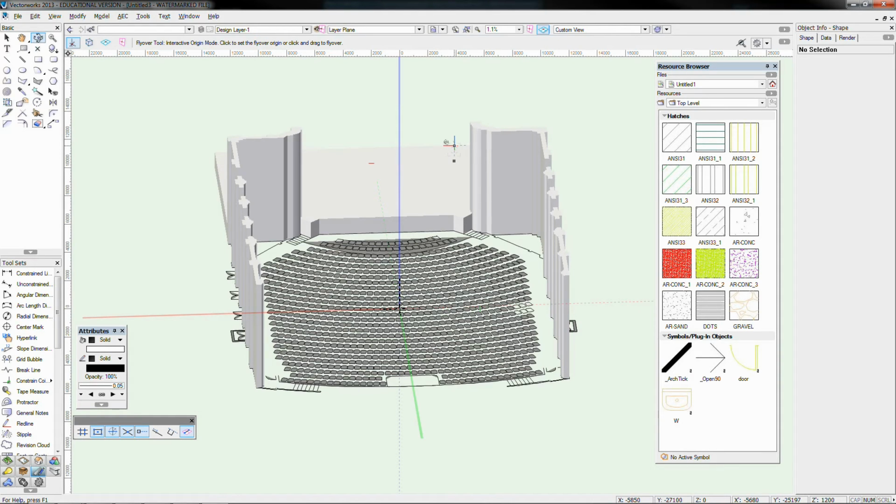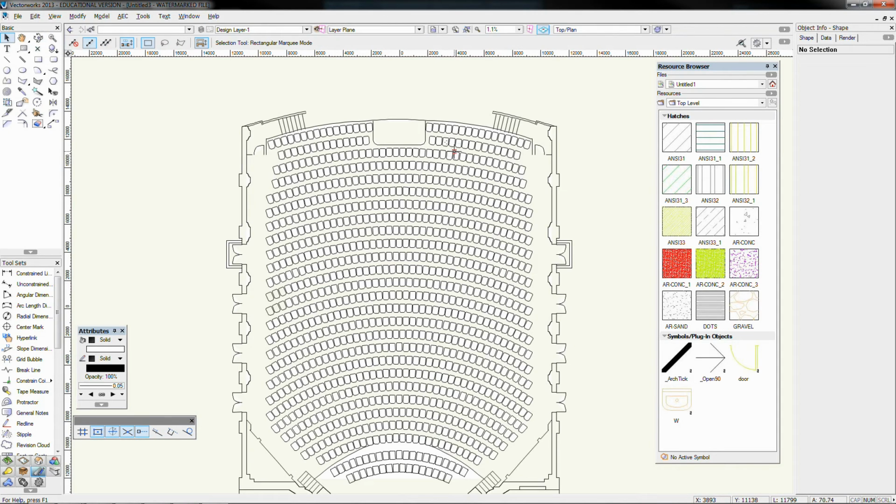And you can see that took me, what, no longer than 2 or 3 minutes just to pop that out of the page from a PDF. So that's the great advantage in being able to tear these PDFs apart, steal their vector data, and if they've been drawn properly or exported properly, you can do exactly this with it. Obviously I could have composed all those lines as well and brought it through that way.